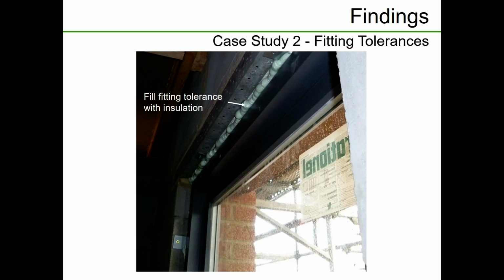Okay, but the point is, it's not just an air gap. The amount of these I've seen where it's just an air gap, that does affect your thermal bridging quite a lot. Okay, and by and large, if you've got very good walls and very good windows and don't do that, that's where you're going to get the problem. That's where you're going to get the moisture.